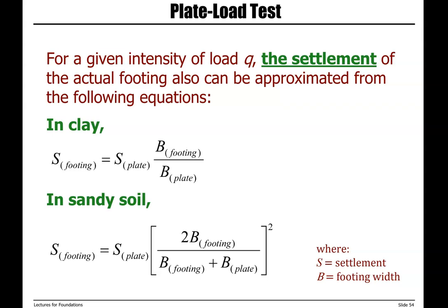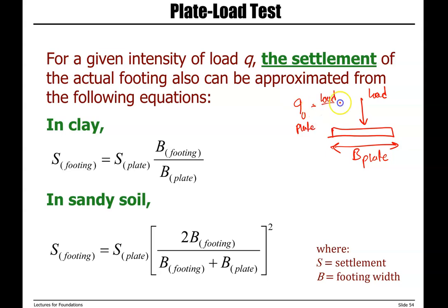Same thing for the settlement calculation. Again, we have a plate with a certain width, apply load, and calculate bearing capacity of plate as load per area of plate. Also, we measure settlement of plate.